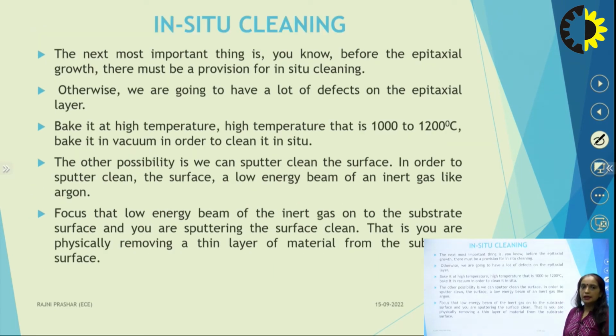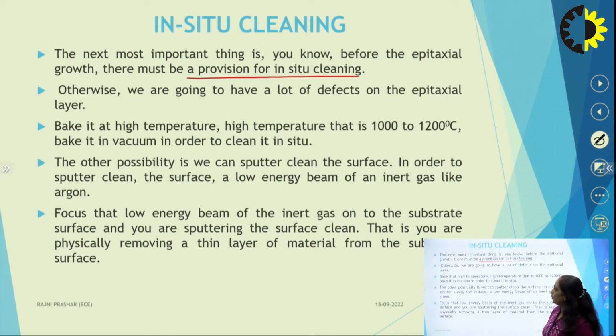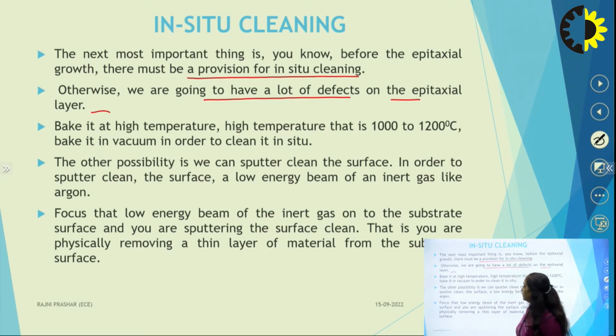Next is the cleaning. Cleaning is a very important part of molecular beam epitaxy, and it should be in situ cleaning, that is, cleaning of the wafer inside the chamber. So before the epitaxial growth, there must be a provision for in situ cleaning, otherwise we are going to have a lot of defects in the epitaxial layer.